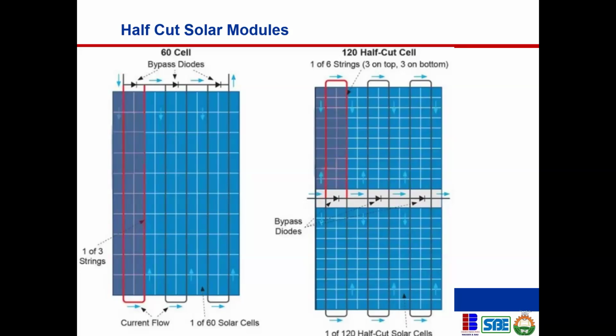And that is why it is important that sometimes when we have these PV systems, you have a monitoring system. The PV module that I have in my house, I can monitor it from anywhere. At every point, I can see what it is producing, and because of this, I'm able to track its yield, and I'm also able to see its performance ratio, right? So sometimes some of these things you're talking about can be mitigated or can be understood by looking at existing projects and seeing how some of these things affect their energy production.